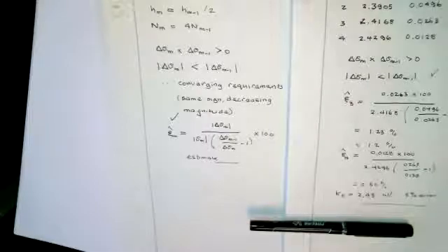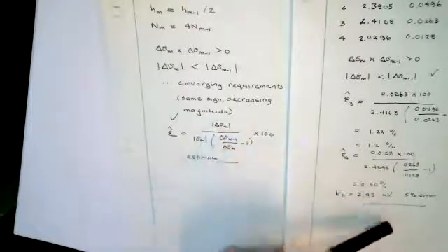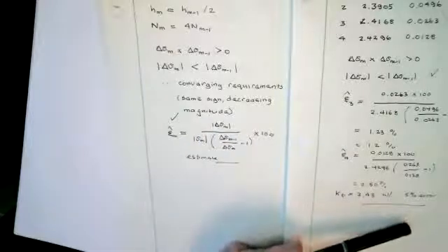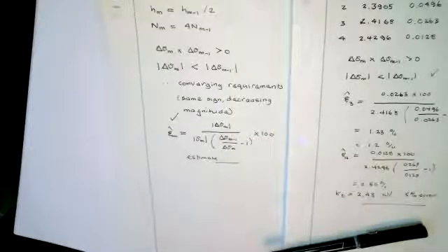When your stress increments are the same sign and decreasing, and when they're small enough, then you'll get acceptable errors. And 0.5%, that's a good answer. That's almost certainly 3 figures here, and certainly 2. And 2 figures is not bad in stress analysis. Not bad at all. Strengths vary by at least plus or minus 10%, sometimes more. So your stresses are pretty good compared to your strengths. Any other questions?